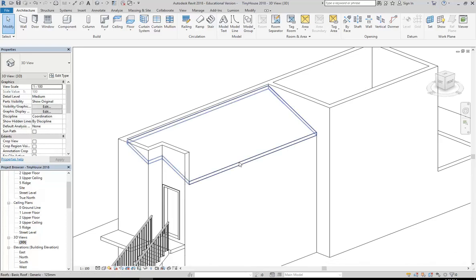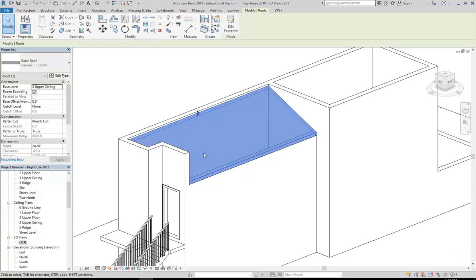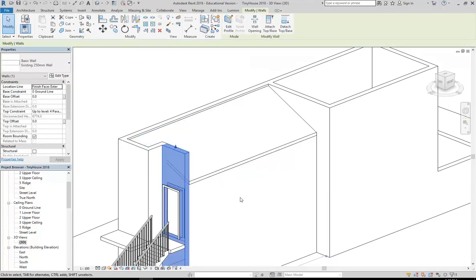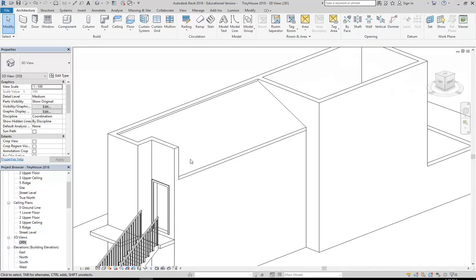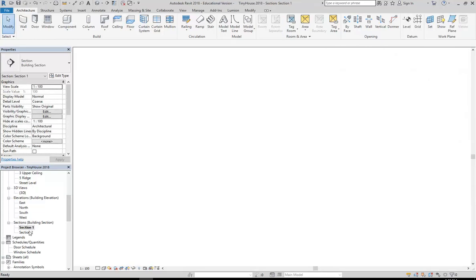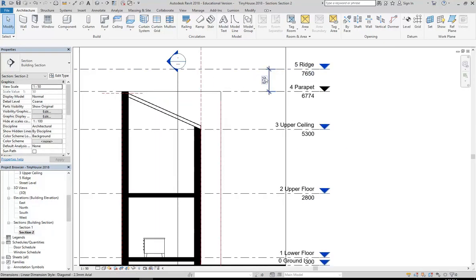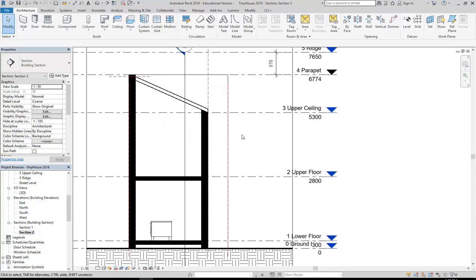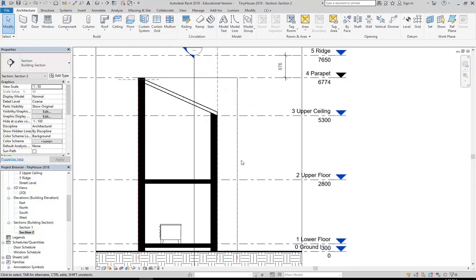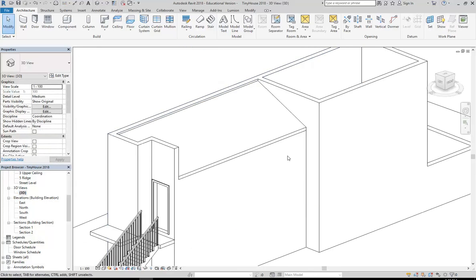The important thing is the roof sits on this wall, it's got the parapet in front of it, and it's quite normal to adjust your set out points and change the way you measure things as you go throughout a project. As long as you're working from the same set out on the ground, it should work. So anyhow, I'll give some time to try and get to that point.